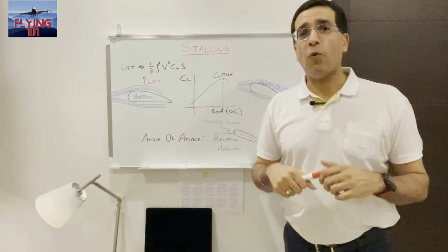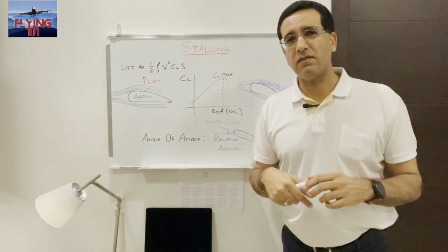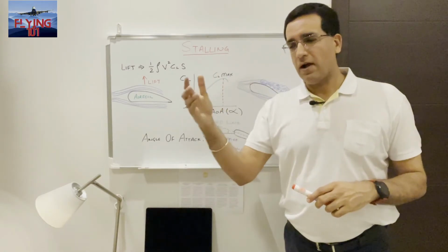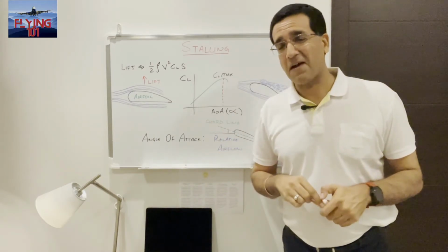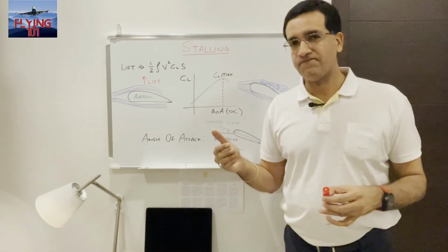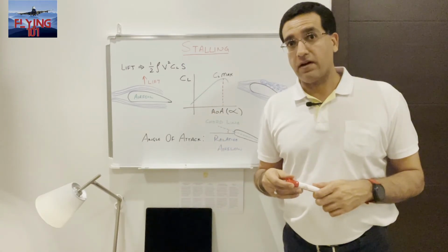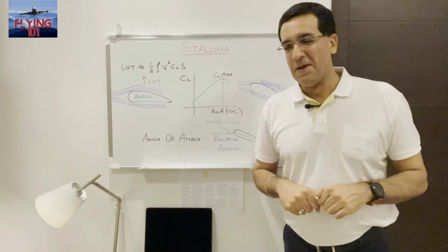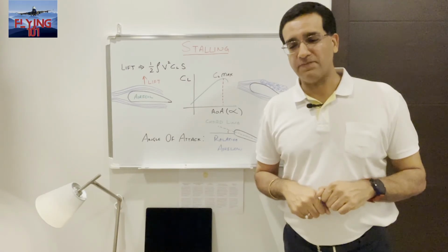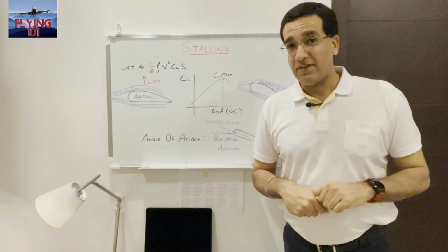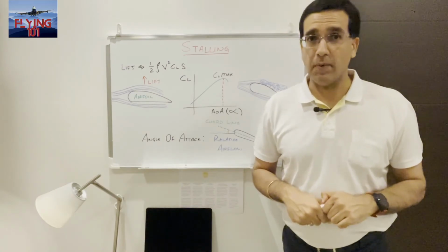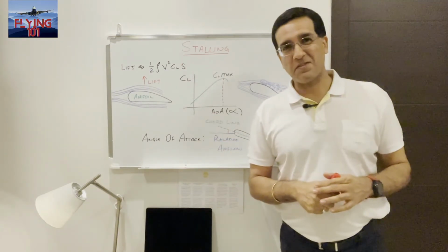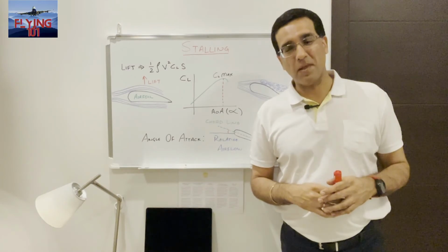Aircraft may even have a stall warning device or a tactile feedback mechanism for the pilots. So there might be an aural warning system on board to alert pilots that the aircraft is about to enter a stall, and so they know that this is something that needs to be addressed immediately. It's quite a critical phenomenon, and it's something that pilots are trained to understand quite deeply, the implications of it and how to recover from it. All right, so there we have it. What causes stalls and how to recover from them.